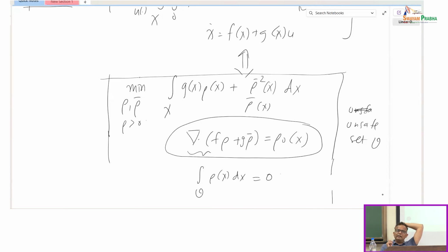And these can be constructed analytically. So the beauty of this is, as opposed to the barrier function or the navigation function. So how do you solve the safety problem in a primal setting? You solve the safety problem in a primal setting using so-called navigation functions. So what are navigation functions? Navigation functions have this physical interpretation: imagine that you have some unsafe set and you want to construct a function, and you have an unsafe set, you have some initial point, you have a target point.